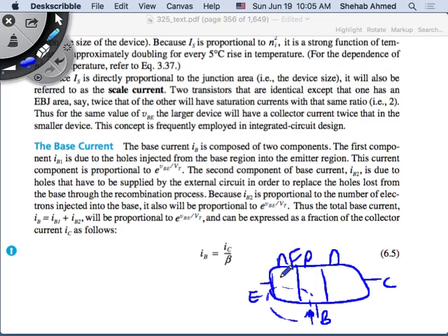We said that most of the electrons that actually go from here across by diffusion will continue going through, right? So these electrons don't stay in the base, and since I made the base small, and I made the voltage here such that there's an electric field, as soon as these electrons pass through, they jump over to the collector side or collect on the collector side. Then the emitter current IE and the collector current IC will be very similar. We will see how similar they are, right?